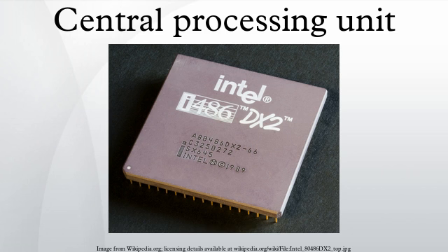It is not at all uncommon, therefore, to see 4 or 8-bit microcontrollers used in modern applications, even though CPUs with much higher range are available. The simpler microcontrollers are usually cheaper, use less power, and therefore generate less heat, all of which can be major design considerations for electronic devices. However, in higher-end applications, the benefits afforded by the extra range are more significant and often affect design choices.